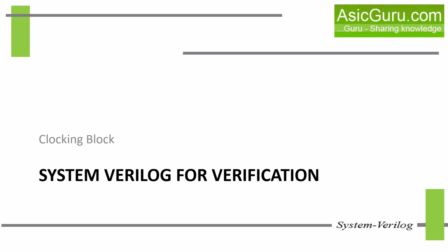Hello everyone. Today we are going to explore another important concept used in test benches, that is the clocking block. When you build a verification environment, then definitely you will deal with timing challenges, means when you need to sample your signals and you need to drive the values. So this is where SystemVerilog's clocking block comes into picture because it helps you in coordinating the signal activity with the clock, and thus it makes test benches more predictable and more timing accurate.